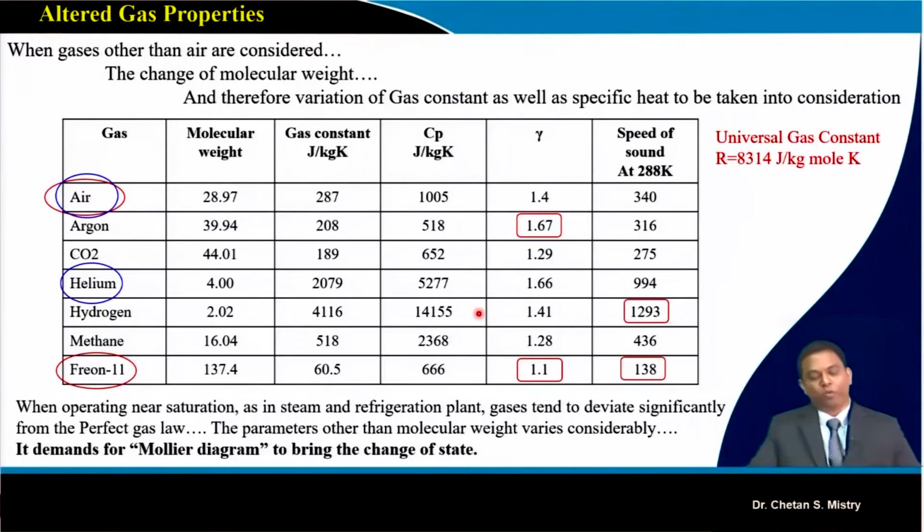These days people are moving towards the application of cryogenic fluids. For cooling applications, you are looking for helium gas, where you need different kinds of compressors. Helium gas compressors are very common in application. Now in order to test those helium compressors, they use an axial flow compressor with air as the working fluid. That gives the benefit that it rotates at comparatively low speed as compared to when you rotate that wheel using helium gas.